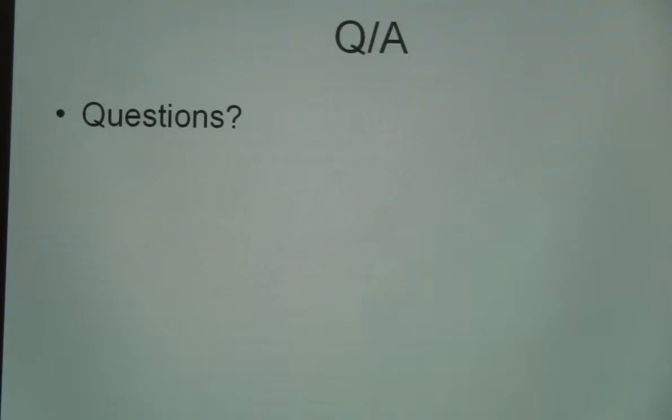Or you might just do a wired OR and a master-slave, and the slaves only respond to requests. Or you could take some of your GPIO lines off the Raspberry Pi and use them to select which Arduino you want to be receiving input from.